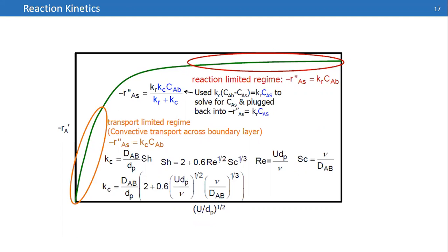If you decrease the size of your particle, you can overcome the internal mass transfer limitation, and then you can see when you can solve this issue. Since, as I said, if you want to have a reaction, your reactants should penetrate inside of your bed. Otherwise, you are losing some internal parts and your reaction rate is not a real reaction rate.